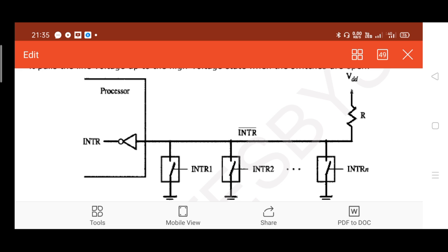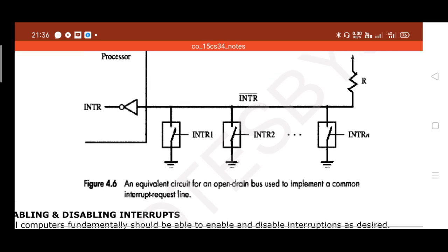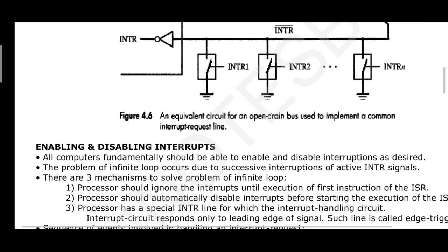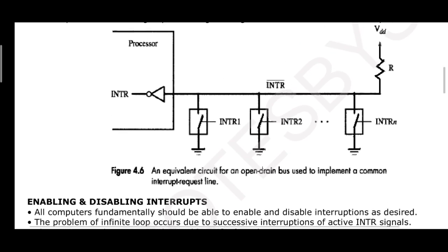If you just close the switch, for example a keystroke may cause the closing of a switch, the circuit will be completed, the device triggers, and the processor will know this triggering. Then the necessary action will be taken by the processor. Please go through all these explanations. If you have any doubt, please ask.